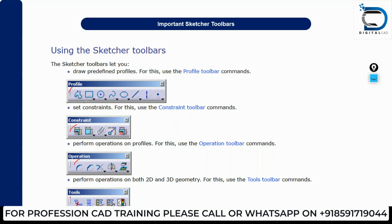In the profile toolbar, we'll create our sketch using the different shapes available directly. In the constraints, we'll apply the dimensioning. In operation, we'll clean our sketch. If any extra line is not required, a trimming operation is there. All these operations are present in the operation toolbar. And in the sketch tools, you can do the sketch analysis after your sketch completion.